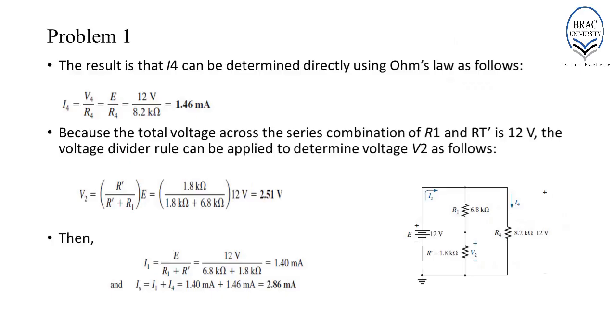One thing which you must remember while redrawing the network is that you cannot change the polarity of the potential drop across the resistors or the polarity across the source. You can also not change the direction of the given currents. Remember, we are redrawing the network to simplify it. We cannot change the design of the network.